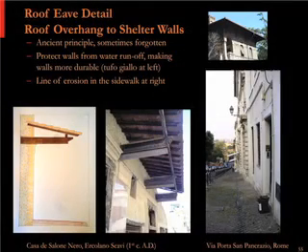The part that's going to rot anyway is the part of the triangle we don't need, so let's just cut that off. And then the one further refinement is, if that's just a simple sloping underside, if water does get to it, then we want to be able to get it off before it goes in again. So then you build in all these little drip edges. So what looks like an ornamental piece at first glance, this highly intricate cut of that supporting member, is really just perfectly evolved and integrated for the structure, the long-term durability, the architectural expression, and the water management.